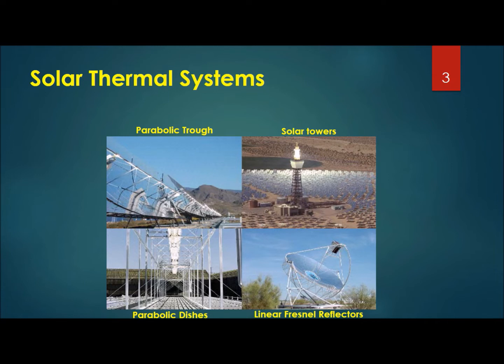Heat transfer fluids such as synthetic thermal oil, suitable for temperatures up to 400 degrees centigrade, circulating through the tubes are used to generate steam through heat exchangers and steam generators and drive a turbine to generate electricity through a steam cycle. This is a well established and proven CSP technology.